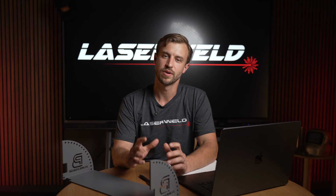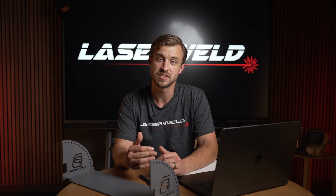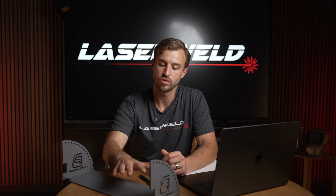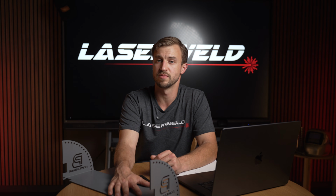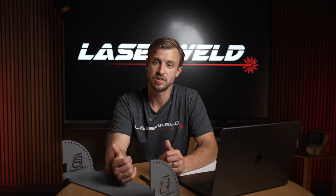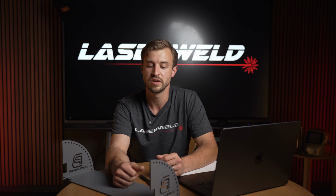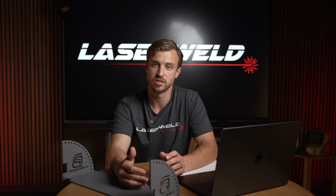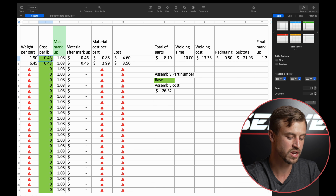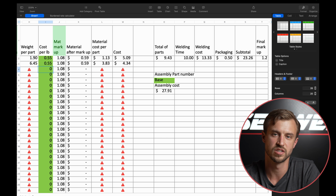When you're working up these quotes, I would highly suggest you do it in Excel or some other sort of spreadsheet, and then save it with the part number and the date. That way you always have it. So say you quote this part, you submit it to the customer, you don't hear back from the customer for a year. We've had that. When they come back to you, you pull up your quote and say steel prices, now it was 43 cents back then, now it's 56 cents a pound. All you have to do is just update your material cost. And immediately, we'll go ahead and do that right now. So let's say it was 43, now it's 55. So now this part now costs $27.91.